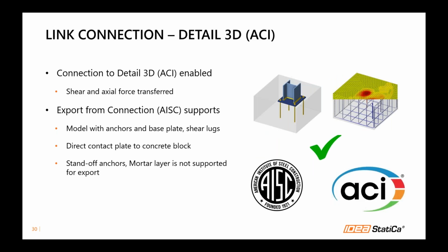The ACI implementation doesn't end here. Another new functionality or implementation is that IDEA StatiCa Connection application for steel connection design is directly linked to IDEA StatiCa Detail for concrete checks. That means that whenever you design a base plate connection, and you want to check also anchorings, including the real reinforcement influence. This is quite useful in all cases where concrete breakout resistance checks fail. Then you may use this link.